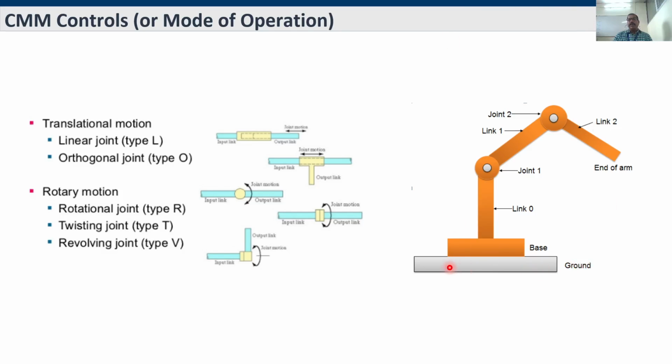And here you will have the joints and links, how they are connected. There is a ground base, this is called a link, and this is called a joint, and this is another link, here also a joint. Here you will have the end effector. The end effector will be decided according to what kind of product or object we are going to handle, whether it's a glass type or whether just two fingers are enough to pick something.